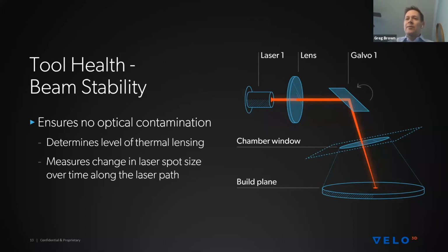Now, one of the really critical aspects of this, or any laser powder bed fusion process, is what is the actual spot size of my laser? That matters because each of the different processes that you use to make a part can be very sensitive to the actual spot size of the laser. In many cases, if you're looking to fill a large bulk area of a part very quickly and with high productivity, you're looking to use a really high powered process, and that involves needing to defocus your laser so that you don't get really strong keyholes and gas processing that break down the process.